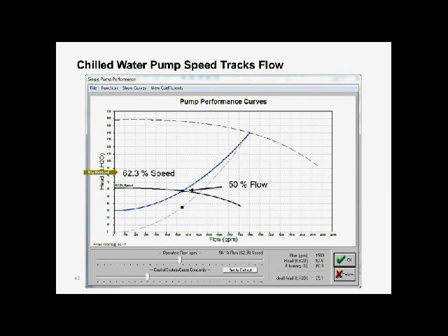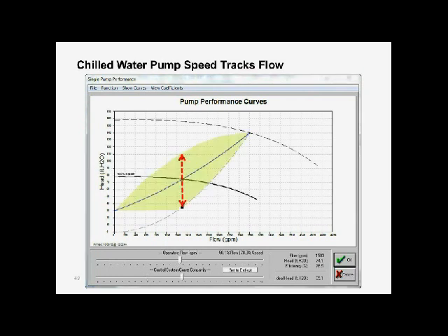It even gets more interesting because it's not really a curve it follows, it's an area. What happens with chilled water pumping is that I could be operating down here or anywhere in between. If I'm up here, when I'm in the perfect condition, I'm following as ideally as I can. All the loads in the building are exactly the same percent load.